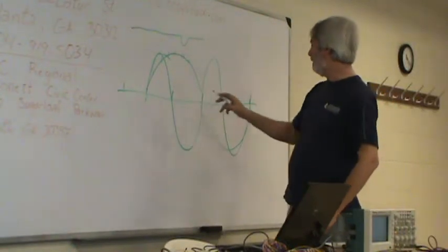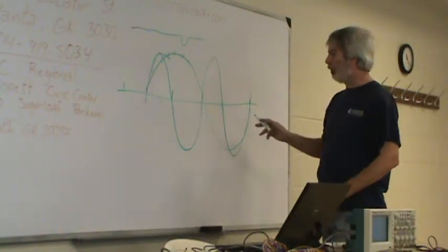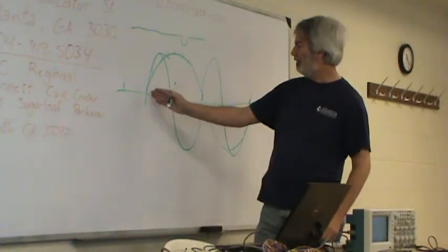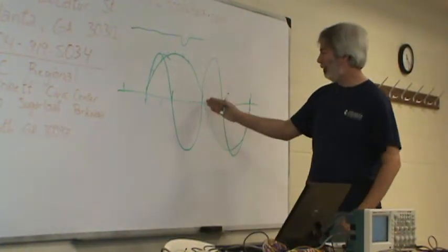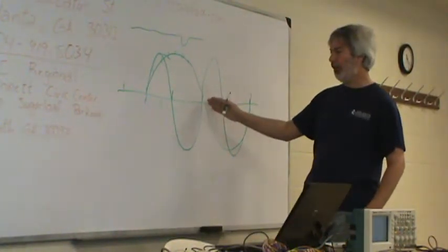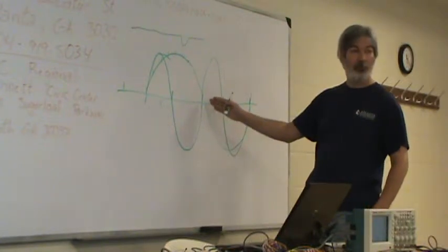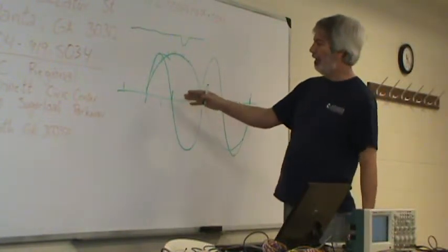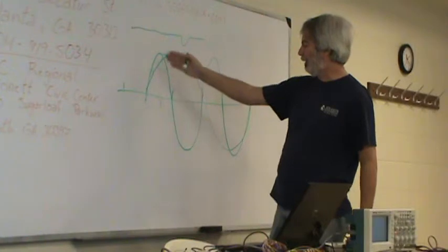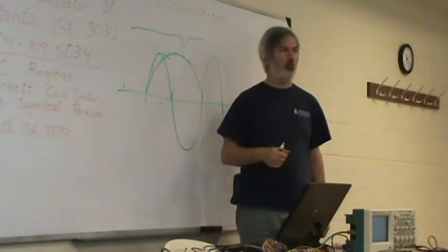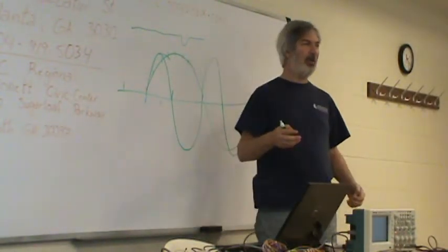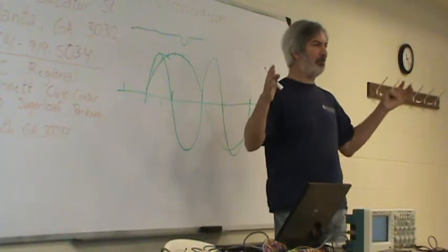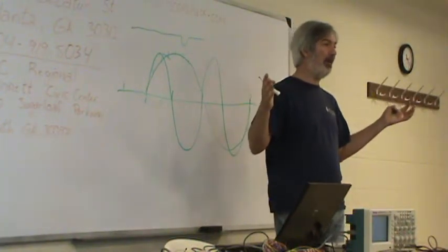Essentially what's going to happen is it's not going to show it properly because every time that it samples, you're actually at 0 voltage. Or it may be that every time it samples, you're at some voltage. And what the scope will do is try and fit a curve that matches those points, and it won't find it.